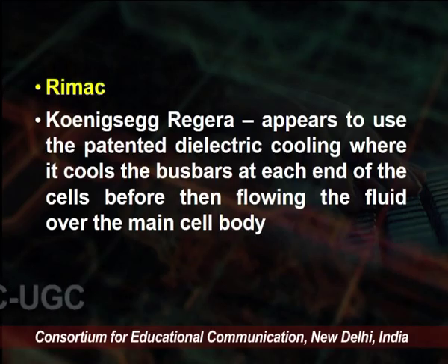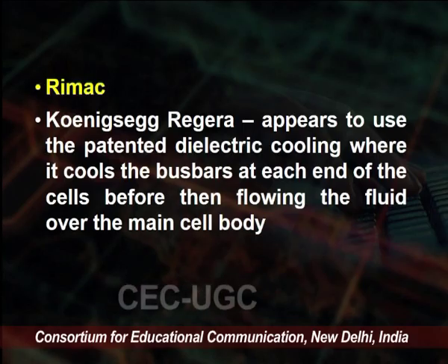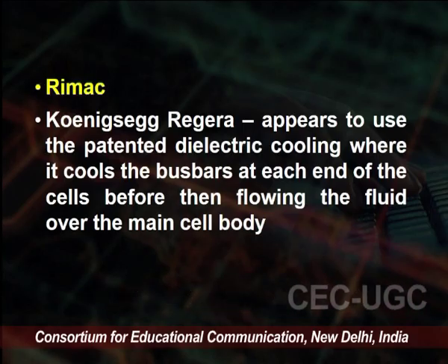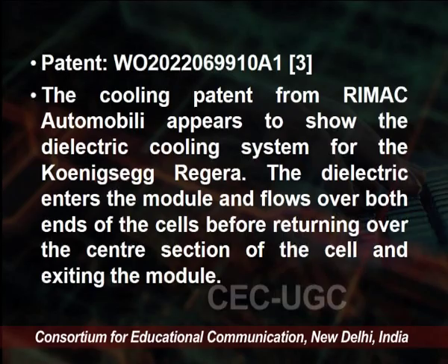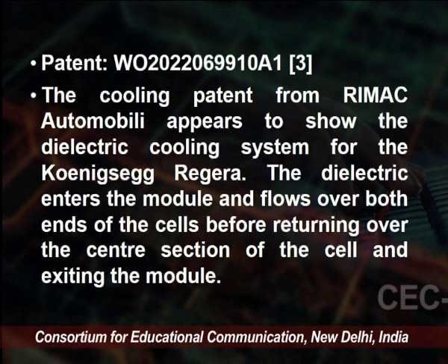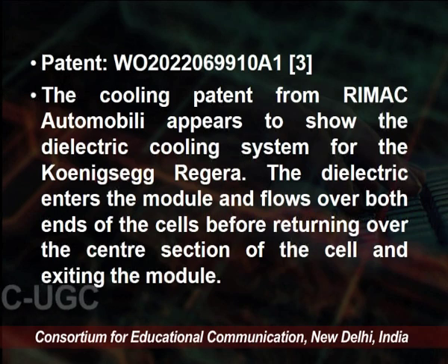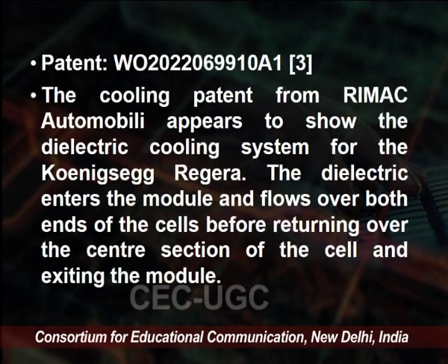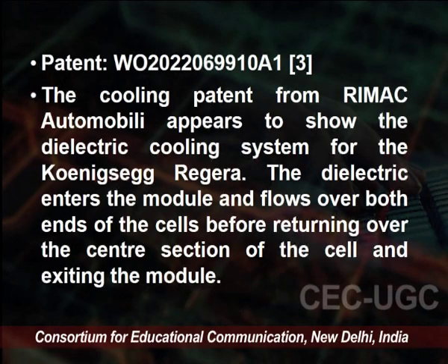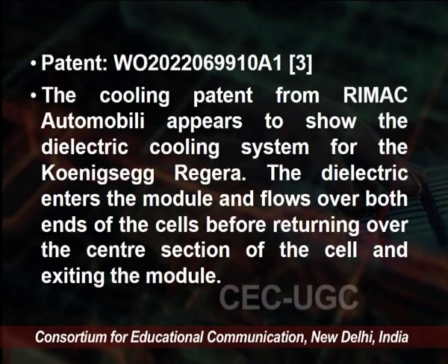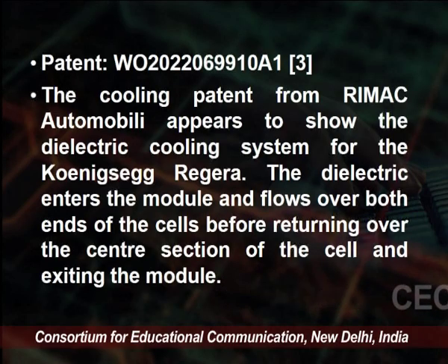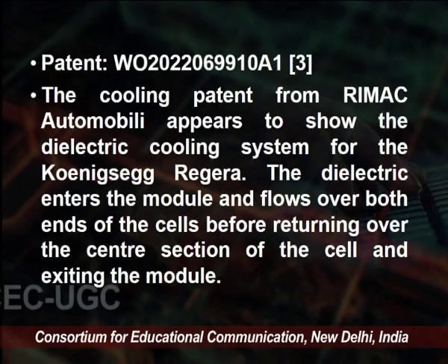Rimac appears to use patented dielectric cooling, where it cools the bus bar at each end of the cell before then flowing the fluid over the main cell body. That has been published in the patent, and the cooling patent from Rimac Automobili appears to show the dielectric cooling system for the Concept, where the dielectric enters the module and flows over both ends of the cell before returning over the center section of the cell and exiting the module.